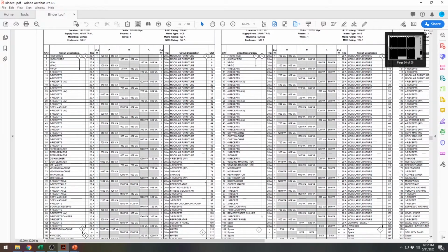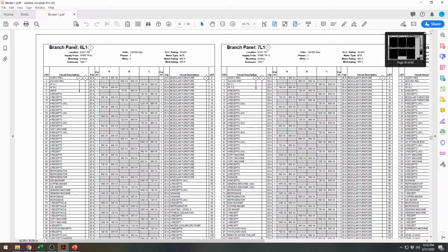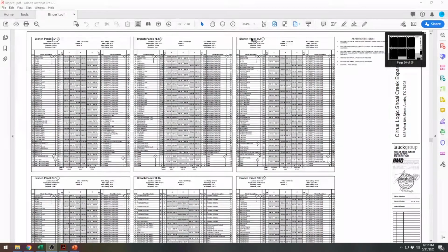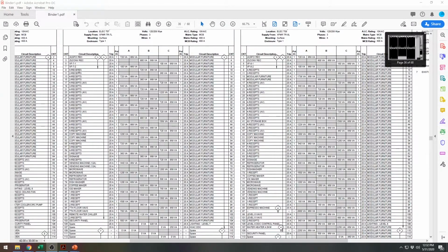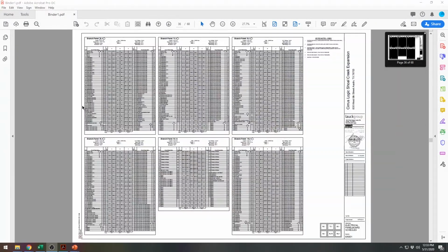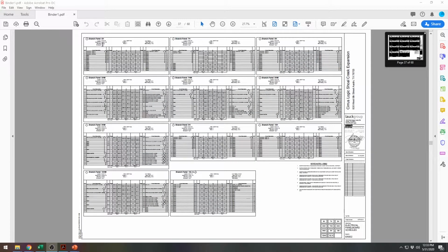And you look at here, so this is your level 6 low voltage, so that means 120 volt panel. You have one for level 7, level 8, and basically everything is labeled what it is and kind of the mechanical equipment and how many receptacles and everything on that circuit. More panel schedules.